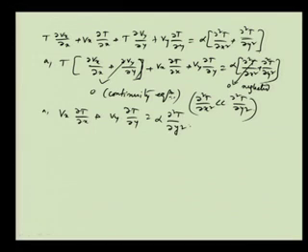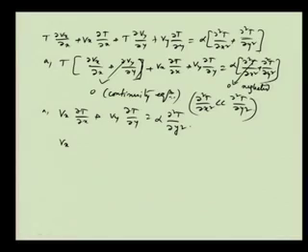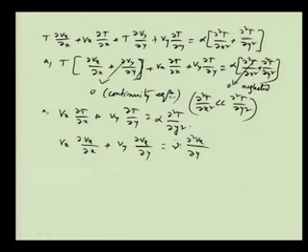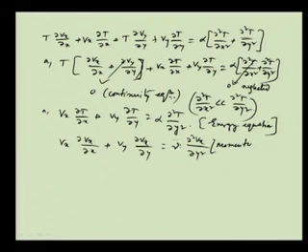And this is becoming the energy equation, and if you see, it is exactly a similar kind of equation to what we developed for momentum. So, what is the momentum equation? It is Vx into ∂Vx/∂x plus Vy into ∂Vx/∂y, the x-directional momentum, is equal to mu into ∂²Vx/∂y². So, this is your energy equation that we got, and this is your momentum equation that we have found out in the last class. We have done the derivations.